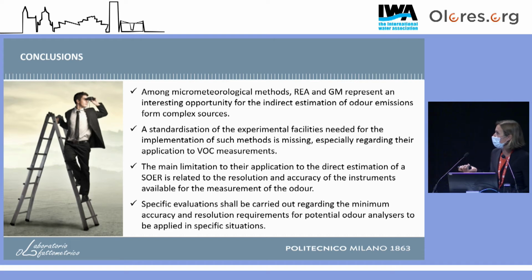The main limitation to their application is still the application of the direct measurement of an odor emission rate is still related to the resolution and accuracy of the instruments that are available for the measurement of odor concentration. So specific evaluations should be carried out to be able to evaluate accurately the minimum accuracy and resolution requirements for potential odor analyzer to be used for such application. However, the last word is not said, we say in Italy, because there can be further implementation which might make this method effectively applicable in the future.